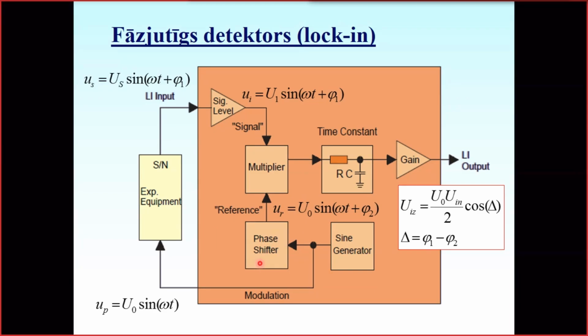Sometimes it may be done in modern meters. It's often done automatically with some feedback system, especially if we have a digital one. Usually the lock-in amplifiers are controller driven. So the controller all the time changes this phase, scans over the phase and records the resulting output.